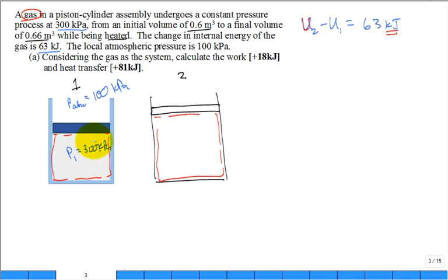Professor, is that gauge pressure or absolute pressure? P1, 300 kilopascal, gauge or absolute? Do you know with confidence, or is it a 50-50 guess? In this class, for this type of problem, especially as you work through other problems and read the textbook, you'll find that when they specify a pressure like that, it's absolute. It's very rarely gauge, and they have to make it clear that this now is gauge pressure. Otherwise, it's absolute pressure. And you look in the steam tables, it's all absolute pressure.